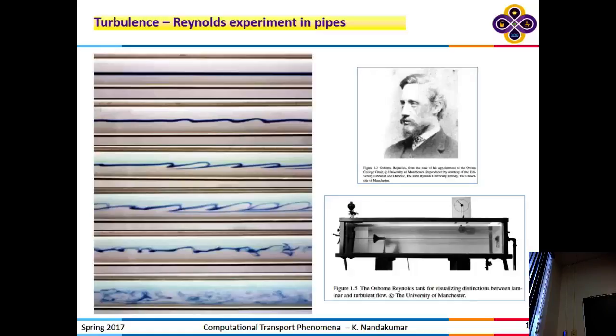In the sense, do you know at what Reynolds number it becomes turbulent in pipe flow? 4,000, 2100 you might have seen. Somewhere between 2100 and 4000, there's a transition regime that you will see in the friction factor chart, right? But nobody has been able to compute the critical Reynolds number from theory. Taylor did a beautiful job of predicting the transition from one-dimensional to two-dimensional flow for the Taylor-Couette flow. It occurs precisely at 1708. Theory predicts it, experiments confirm it. But in this particular case, there is no theory that predicts it will become turbulent at 2100.